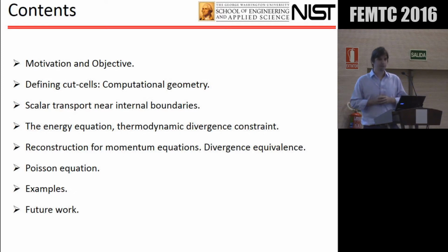Also, these are equations that we need to resolve and solve around our geometries. And the reconstruction for the velocity, the momentum equations, what is it that we propose and we are employing at this point. I'm going to talk very briefly about, within this coupling with the momentum equations, the scheme we use in order to advance them. There is what's called a projection method. I'm going to talk a little bit because there appears a particular equation that needs to be solved. I'm going to talk briefly about that.